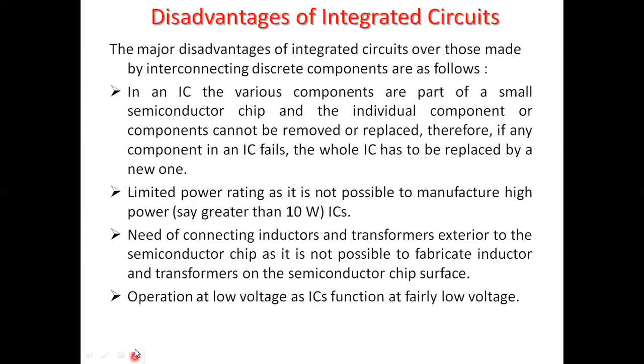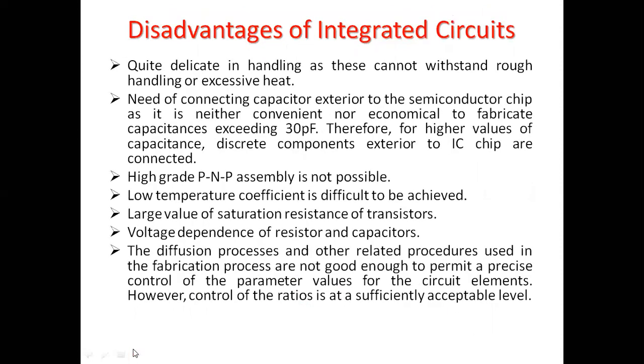Now let us move to the next slide. Now the disadvantages are continued. ICs are quite delicate in handling, as they cannot withstand rough handling or excessive heat. Need of connecting capacitors exterior to the semiconductor chip, as it is neither convenient nor economical to fabricate capacitors exceeding 30 picofarad. Therefore, for higher values of capacitance, discrete components exterior to IC chips are connected.